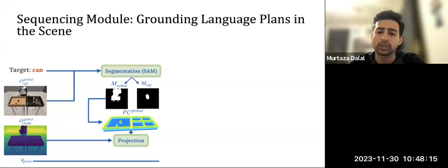We segment the region using a pose estimation system. In this case, the way we implement it is using calibrated depth and segmentation, specifically SAM. And this allows us to have a natural language conditioned pipeline to mask out the object of interest and estimate its pose by averaging the points in the point cloud that correspond to that object.